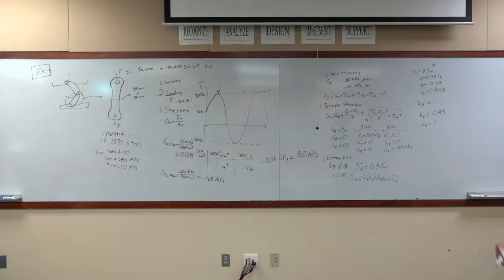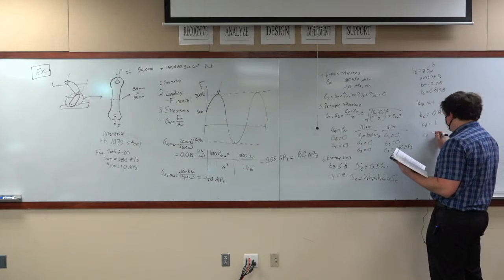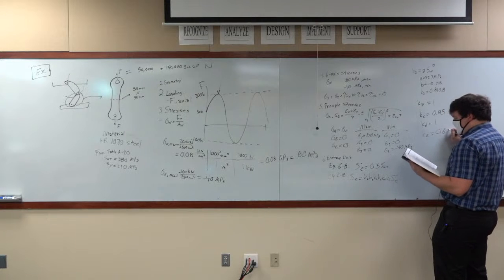Okay, table 6.5 shows you the transformation variable Za. There's the equation for how to use Za. And then there is the reliability factor that's calculated straight for you. Ke equals 0.620.